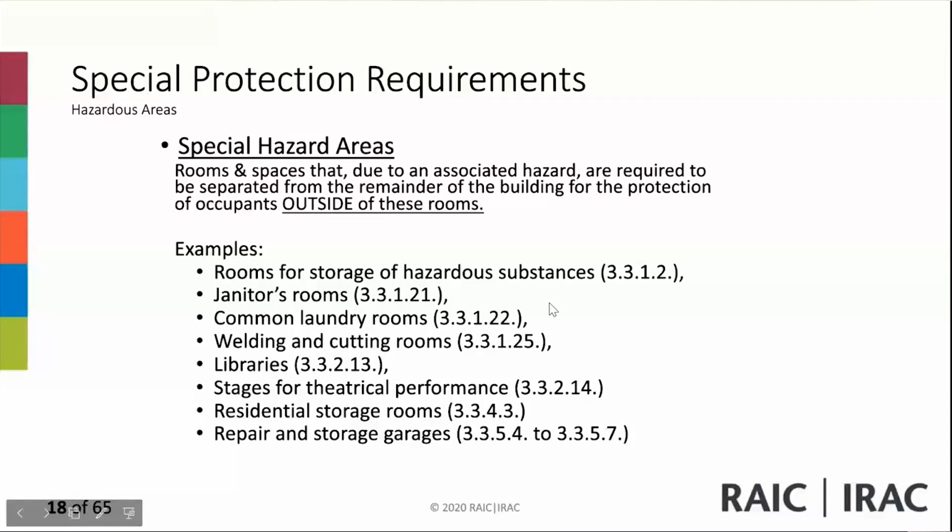And anyway, you have more provisions. Go ahead, Morgan. I have a question on that. If the janitor room is sharing a wall with a suite with a residential unit, would that wall need to be rated between? Oh yeah, of course. Now, if it's just between janitor rooms and corridors, this is separation of... we've got the provisions for residential units and also separation of suites.